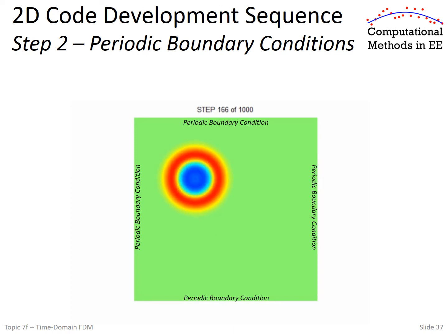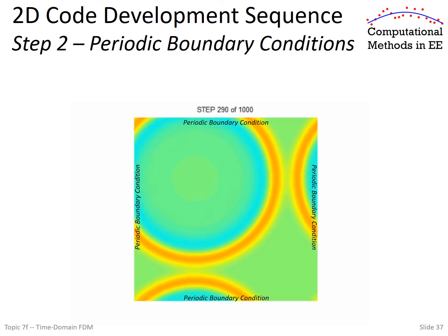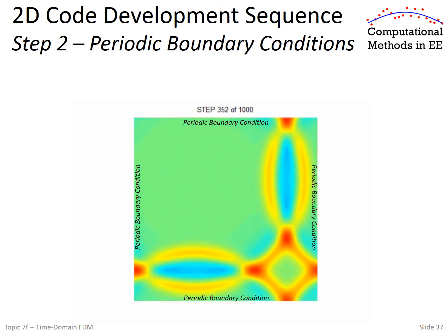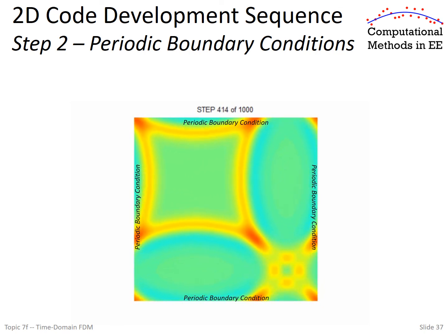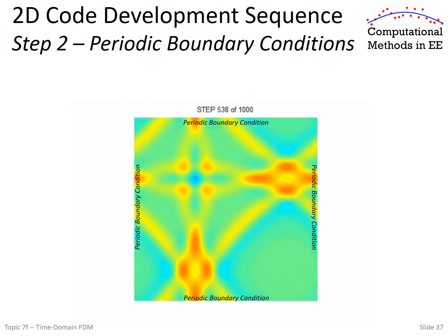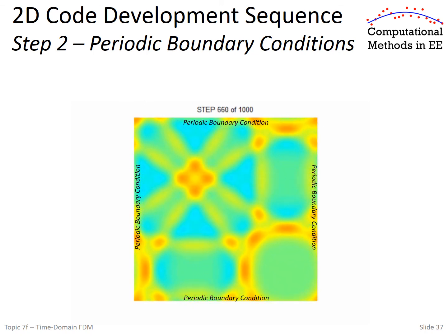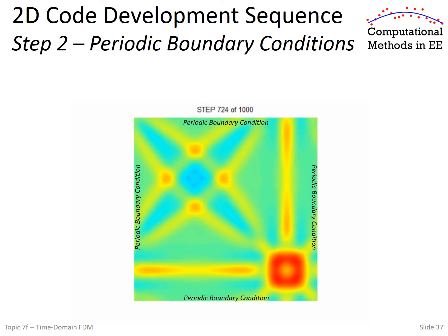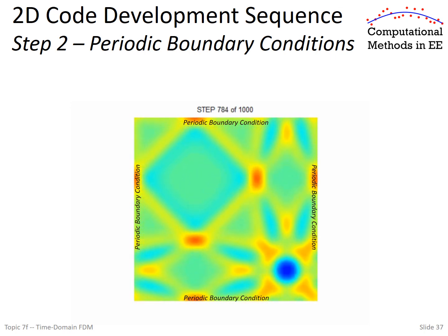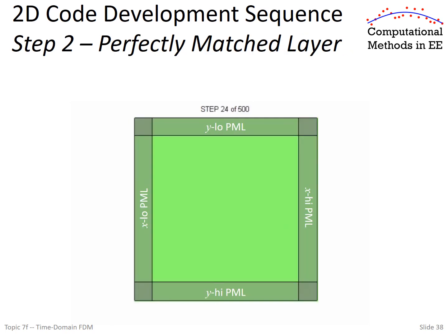And unfortunately, for finite difference time domain, this is just a tough boundary condition. It really makes the code tedious. It makes it not clean. Because the PML is a frequency domain concept, when we bring it into the time domain, it gets a little bit ugly. Conceptually, looking at the simulation, not much new will be happening, but the code's a lot bigger and uglier once we do that.